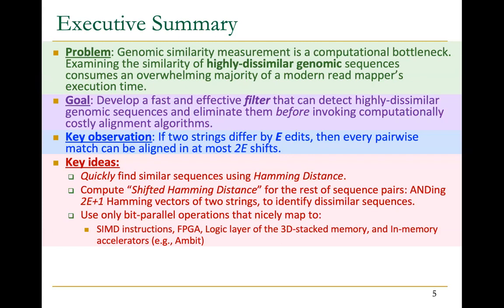Since the operation of the entire algorithm is highly parallelizable and everything relies on bit-parallel operations, this is a really hardware-friendly algorithm, so you can use any hardware platform. You have the option to use SIMD instructions, as published in the SHD paper, or you can use FPGA, 3D-stacked memory, and so on.